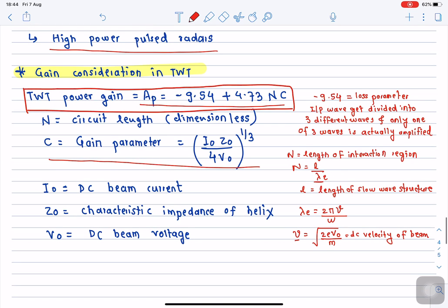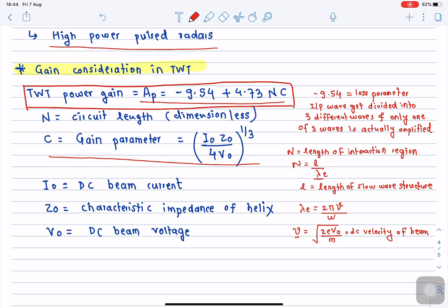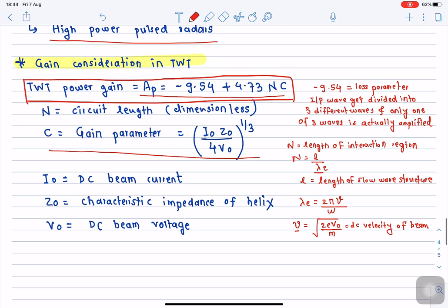Instead, it will attain its maximum amplitude, and then it will start finally decreasing from that particular point. And this particular point at which, with increase in RF input power, the RF output power starts decreasing, we call the saturation point of the traveling wave tube amplifier, right?